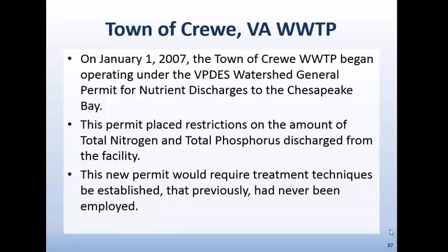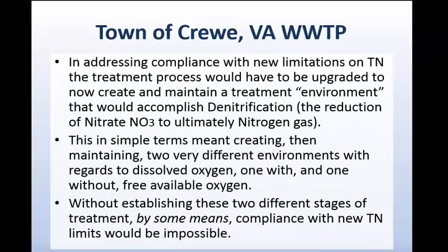Our treatment, which is biological, was really just the removal of the organic content in the form of BOD and complete nitrification. In addressing compliance with the new limitations on total nitrogen, our treatment process had to be upgraded so that we could now create and maintain a treatment environment that was going to accomplish denitrification, which we've never done before. And denitrification is the reduction of nitrate, NO3, to ultimately nitrogen gas. It's really a three-step process. It's ammonia to nitrite to nitrate.